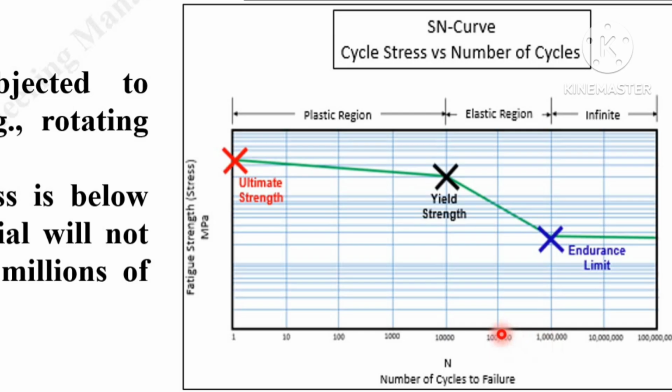The curve is flat after this point. That means the material will not fail below this stress level for infinite cycles.